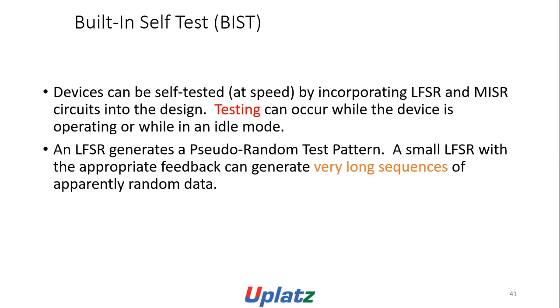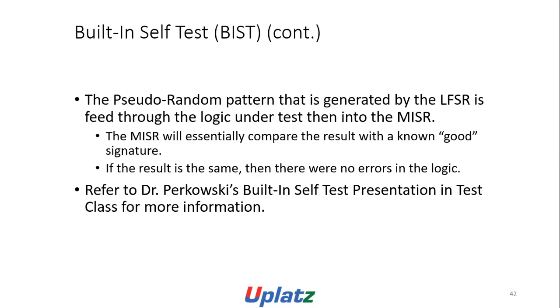Built-in self-test devices can be self-tested at speed by incorporating LFSR and MISR circuits into the design. Testing can occur when the device is operating or while in an idle mode. An LFSR generates a pseudo-random test pattern. A small LFSR with the appropriate feedback can generate a long sequence of apparently random data.